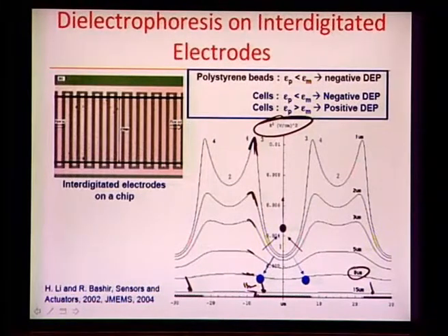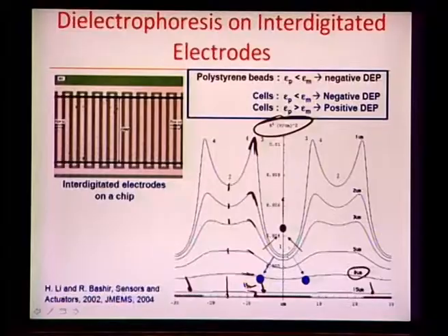Away from the electrode edge, somewhere in between the electrodes, you have a potential well which is created, as you can see here, just because of the fact that here probably the lines of force are most separated, okay, and they are least dense. So, the electric field is smaller, and similarly the same happens on the top of an electrode somewhere in the center, where the lines of force again are probably negligible.